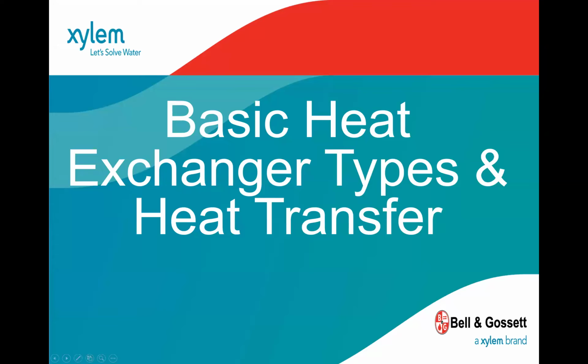And this is mentioned here because in a liquid to liquid situation with no phase change, we need to make sure that we're properly calculating the load and that the sides balance. It's very often we look at a schedule and things don't make sense. Like you'll see the load, say 2 million BTUs, but you'll see a flow rate and a delta that doesn't align with that. Now these are the items that are factored. So just to keep this in mind.